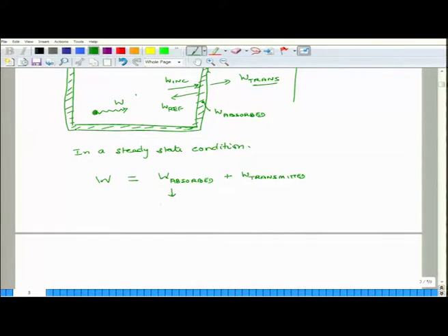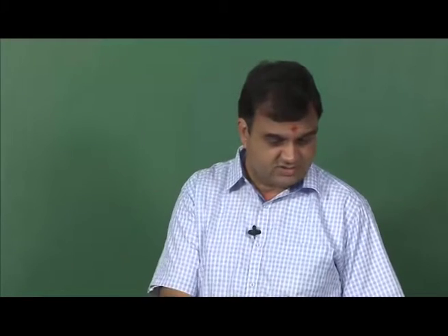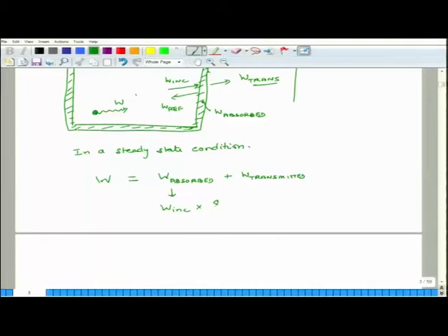So, W absorbed depends on incident energy, incident watts, and times what else? It will depend on how large the surface is and how much is the absorption coefficient of the inside surface. So, it is equal to Sj, if there are lots of surfaces, times the absorption coefficient alpha j of the specific surface, divided by the total internal surface area S naught. So, this is W absorbed.